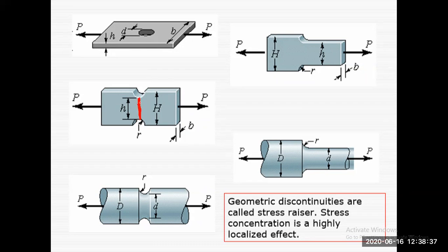So that is why we consider this as the least area portion. Similarly, in all examples, wherever the least area or the discontinuity starts, that is where we determine that it will start breaking at that particular point, right? So in here we consider this as the least cross sectional area. Okay.